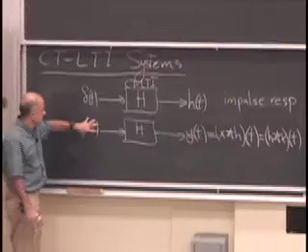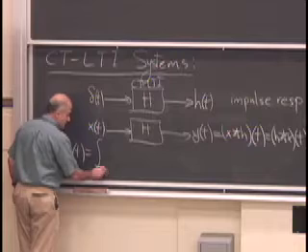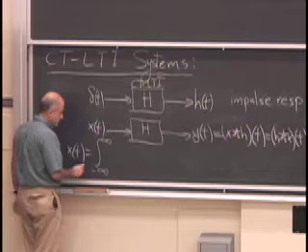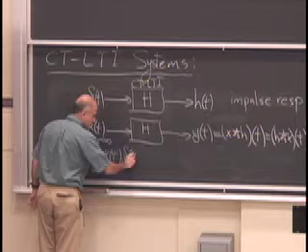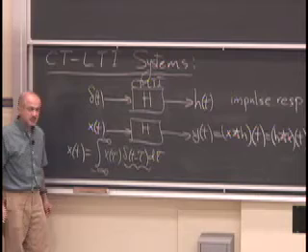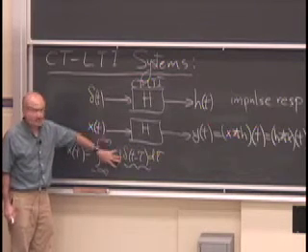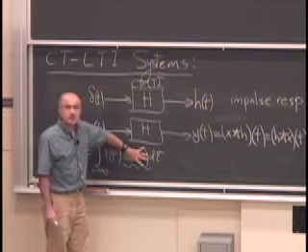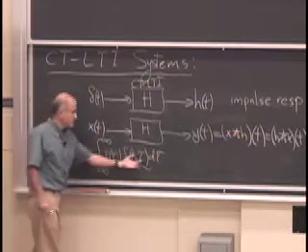And that's because x, any signal x, can be written as a linear combination. Notice in continuous time, our linear combinations very often turn out to be integrals. Linear combination of shifted impulses, where the x of tau is the values of the signal at particular dummy variable instance in time, scale the corresponding impulses, and you can write the signal as this linear combination.